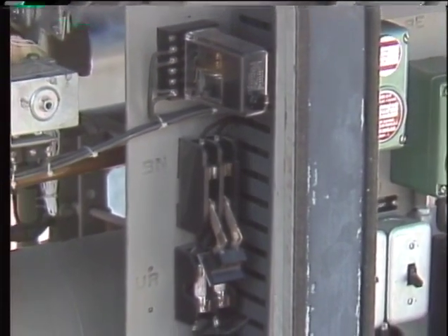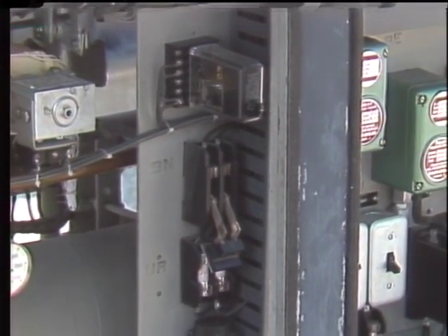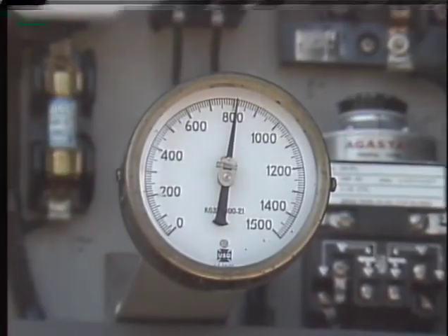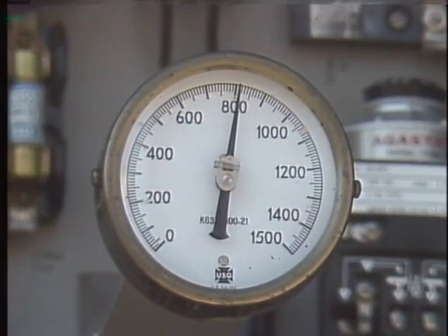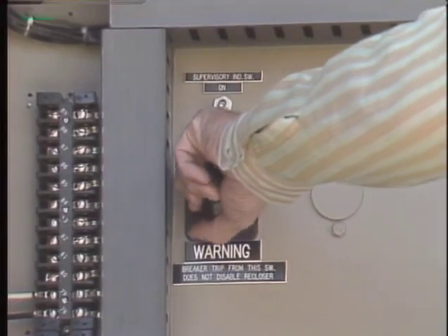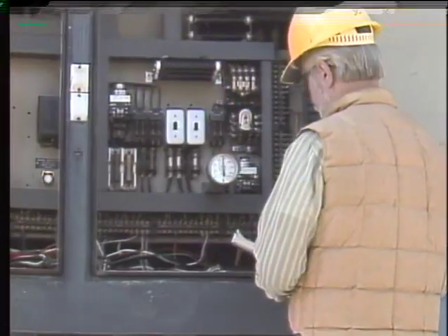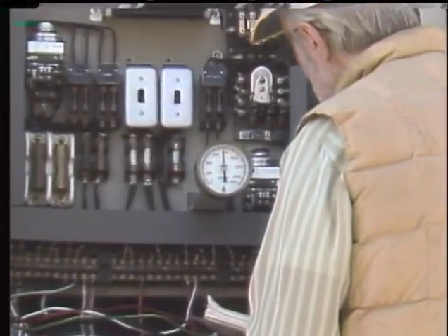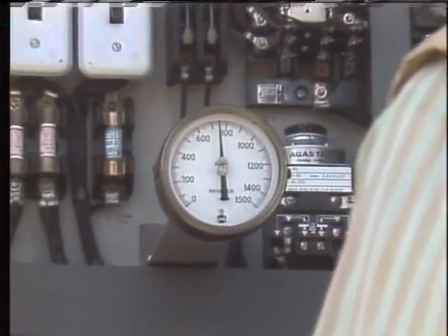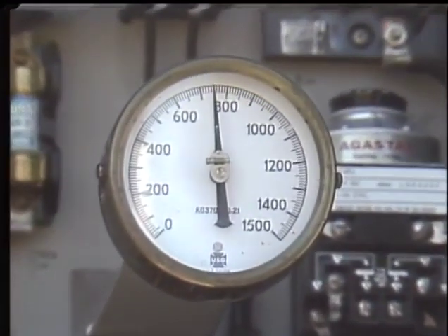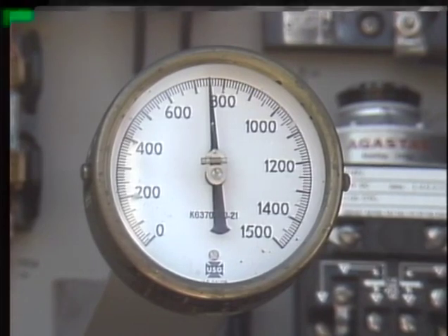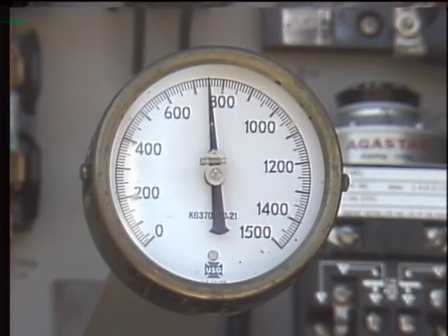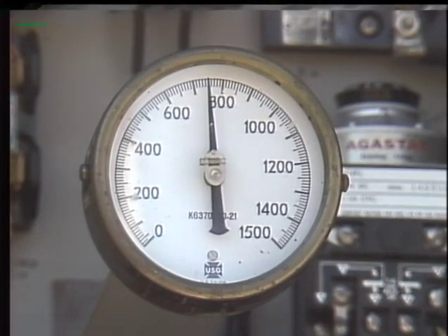Air consumption is the amount of air that is used to trip the breaker and extinguish arcs. To check air consumption, note the head pressure, then trip the breaker. Then check the head pressure again. The difference between the two pressures represents how much air was consumed to trip the breaker. If too much or too little air is used, the breaker isn't working properly. The cause should be located and corrected before returning the breaker to service.